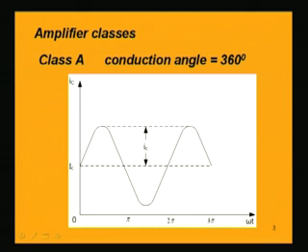Here the DC collector current, which is the Q point, is properly positioned, so that during the positive and the negative half cycle the collector current rises and falls, but it does not enter into the cutoff or the saturation. So, this is a typical linear operation of an amplifier, and this is the class A type of amplifier.